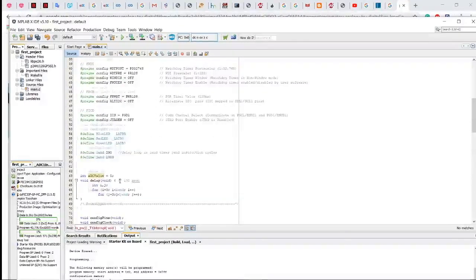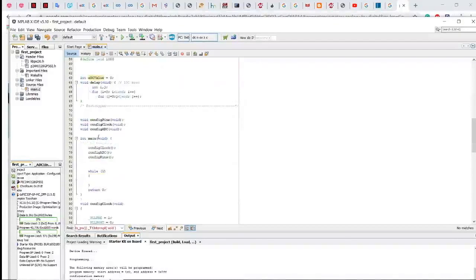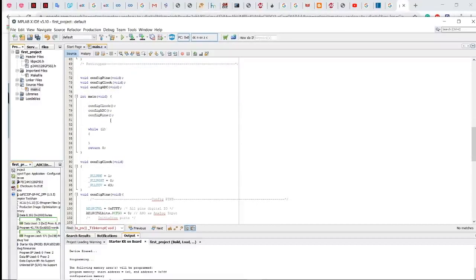And then it's for your reference, because I had some warnings in the compiler, so you need to use the prototypes of the functions, and just in that case you're using void and the name of the function, and then void in the brackets and semicolon, and you will be fine. You are going to remove the warnings.